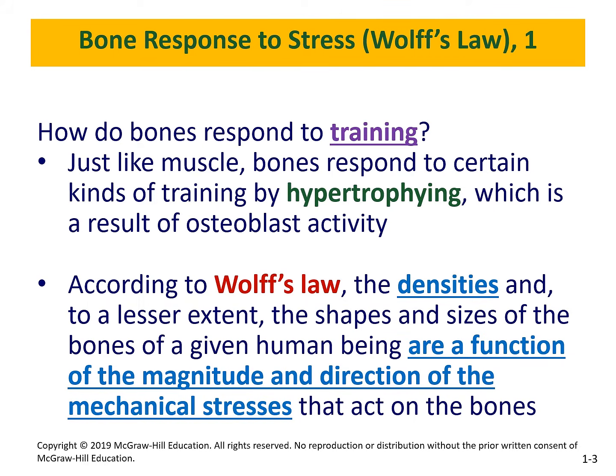One of the biggest problems, remember, we are biomechanical engineers, right? What do you think is the biggest problem for people who have total hip or total knee replacement? Stress shielding, which means that the strong metal is now holding more load than it should, and then the bone around it gets dissolved, and then the implant comes out from its place.